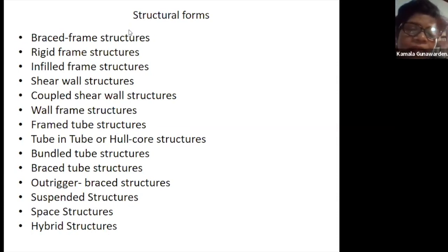In case of continuous slab design, is it required to do the moment distribution at the interior support without using the maximum sagging moment derived from coefficients? No, actually, you don't do anything very special like moment redistribution. If the moments do not match, it is recommended to adjust the moments.